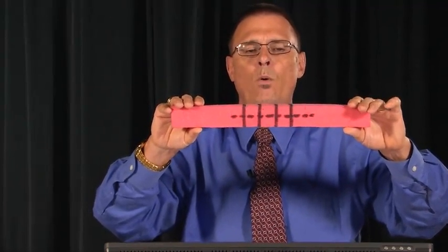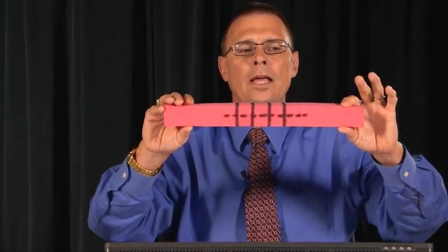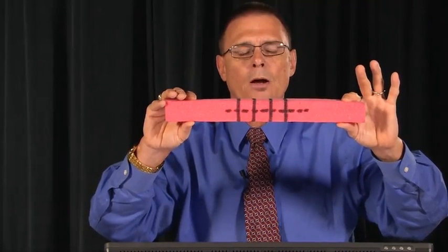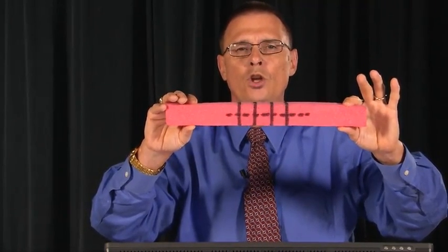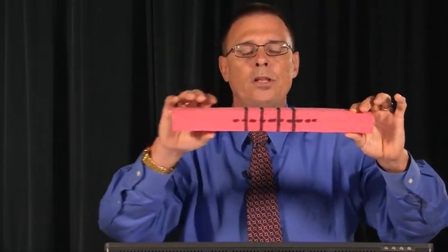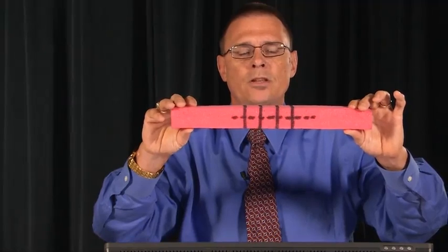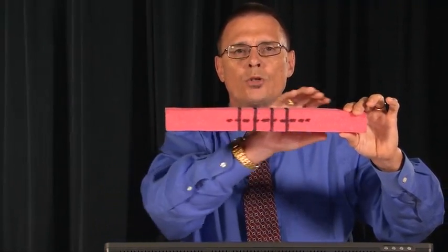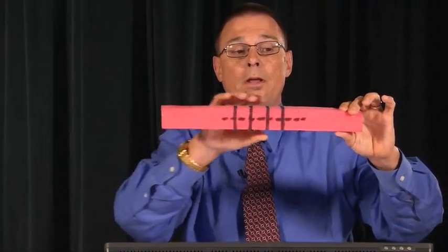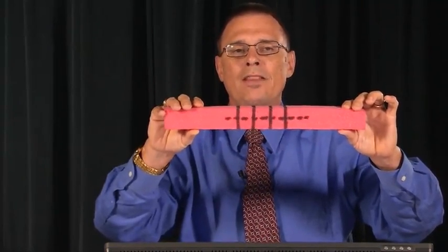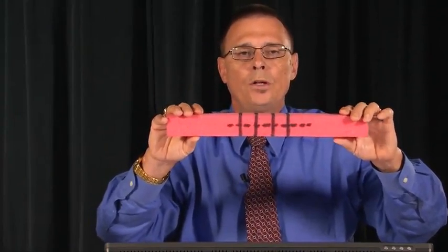It's going to be very important when you later design this member to know what the shear is at particular points and what the moment is at particular points. So we come up with a graphical tool to show those internal shear forces and bending moments at particular places along the beam, and that's the graphical tool we're going to learn in the next few modules.